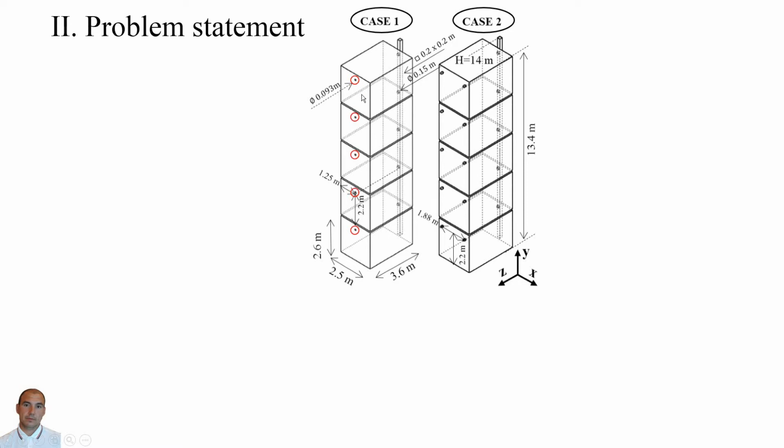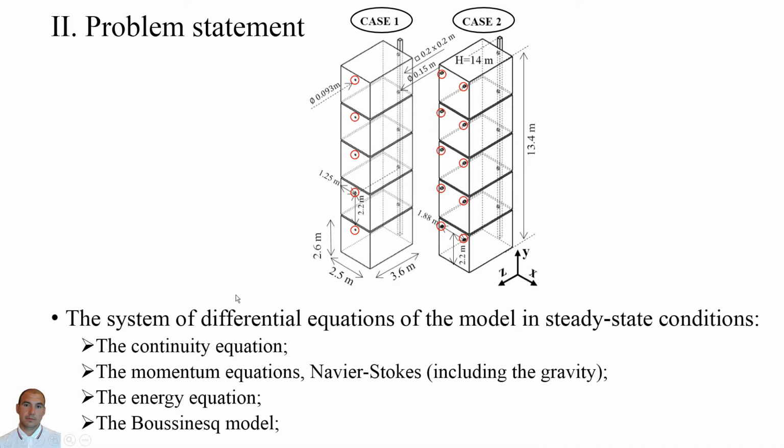In Case 1, air handling units are presented as 5 single domains connected to the main computational domain with 5 inlet vents specified with equal loss coefficients. And in Case 2, air handling units are presented as 2 devices operating as a couple in opposite directions for each room. The CFD models are steady state and describe a 3D turbulent flow induced by mechanical and natural ventilation coupled with underfloor radiation heating, which creates the stack pressure.